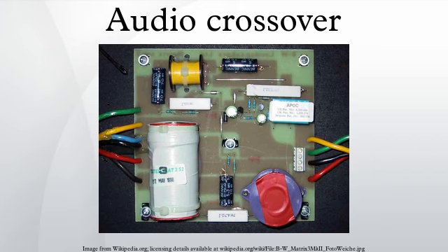Some passive networks include devices such as fuses, PTC devices, bulbs or circuit breakers to protect the loudspeaker drivers from accidental overpowering. Modern passive crossovers increasingly incorporate equalization networks that compensate for the changes in impedance with frequency inherent in virtually all loudspeakers. The issue is complex, as part of the change in impedance is due to acoustic loading changes across a driver's passband. On the negative side, passive networks may be bulky and cause power loss.